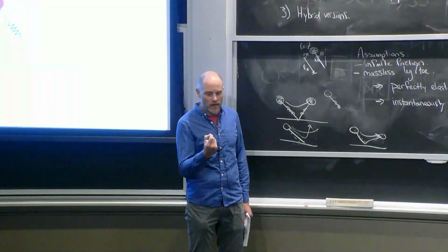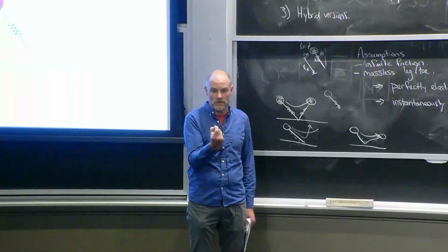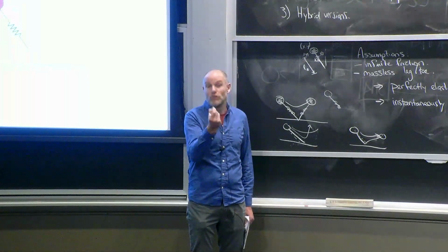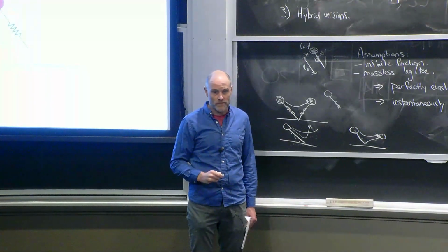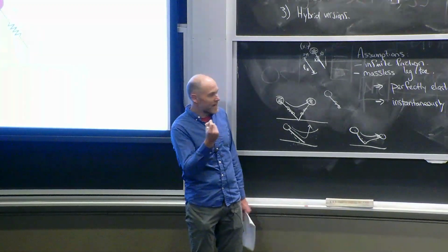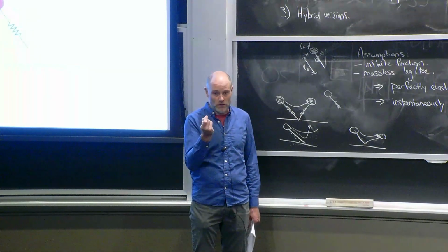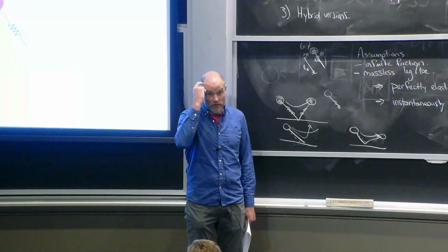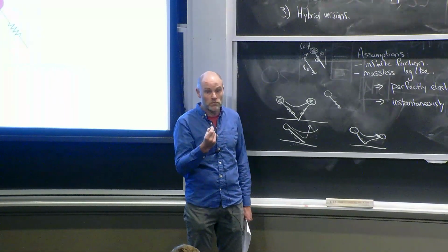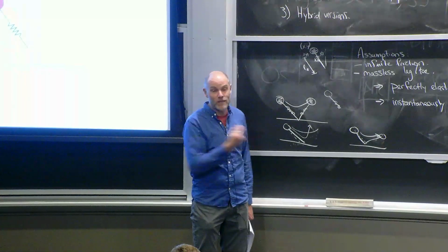Let's say our control objective is specified as stabilizing a stabilizable fixed point. Same thing we did for the other LQR. You want to find some nominal x, u pair that would be a fixed point of the P. And then you can stabilize that point.